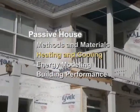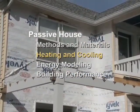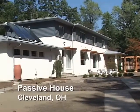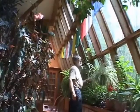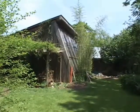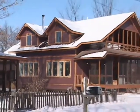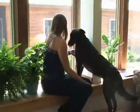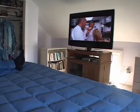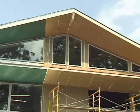The term Passivhaus refers to buildings that are so well insulated and sealed that they no longer need a conventional heating and cooling system. Passivhaus construction is different than passive solar. Passive solar buildings were designed to collect energy from the sun using large areas of south-facing glass, often causing overheating during the day and cooling off at night. Instead, during the winter, Passivhaus buildings rely on keeping in the heat that is naturally present in a building from the sun, people, TVs, computers, and other appliances. And in the summer, south-facing windows are either shuttered or shaded to eliminate solar heat gain, greatly reducing the need